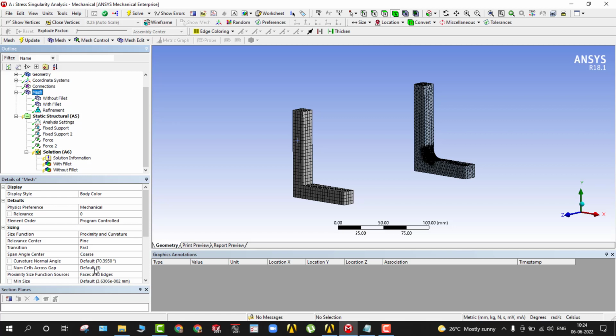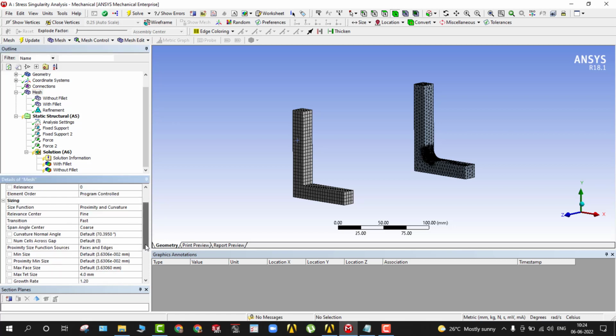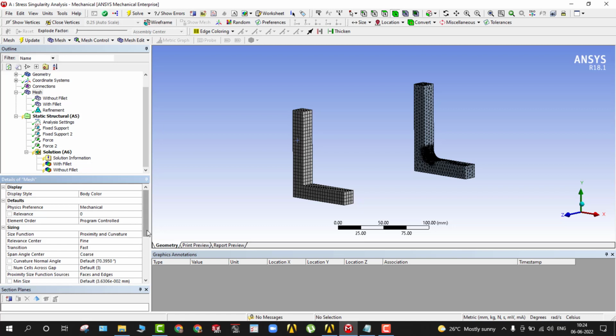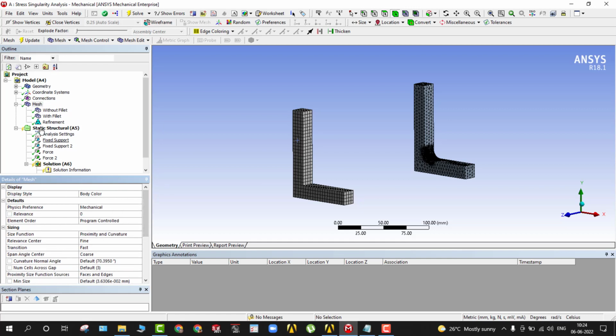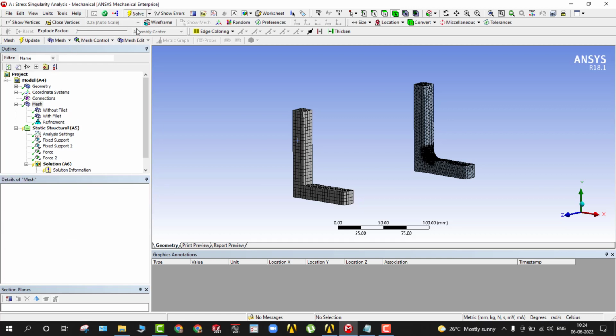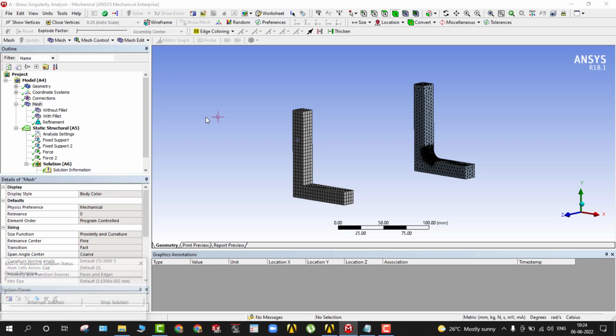The maximum von Mises stress I need into account, and even from the mesh I need the maximum tet size to create the parametric study. I'm just extracting these parameters to compare the results later on.